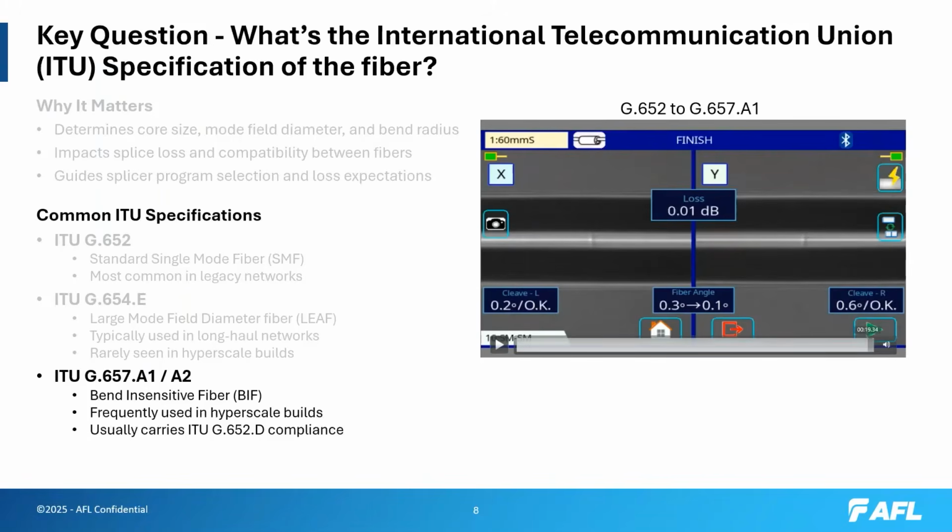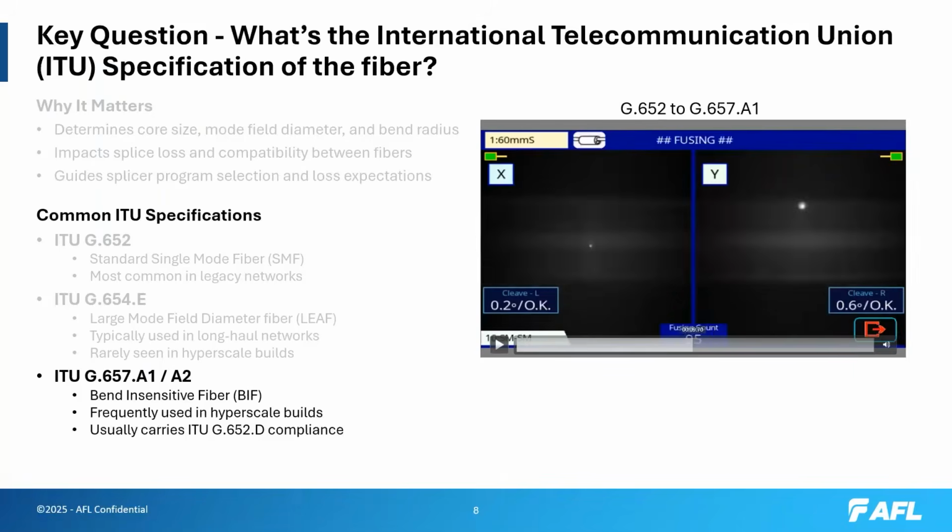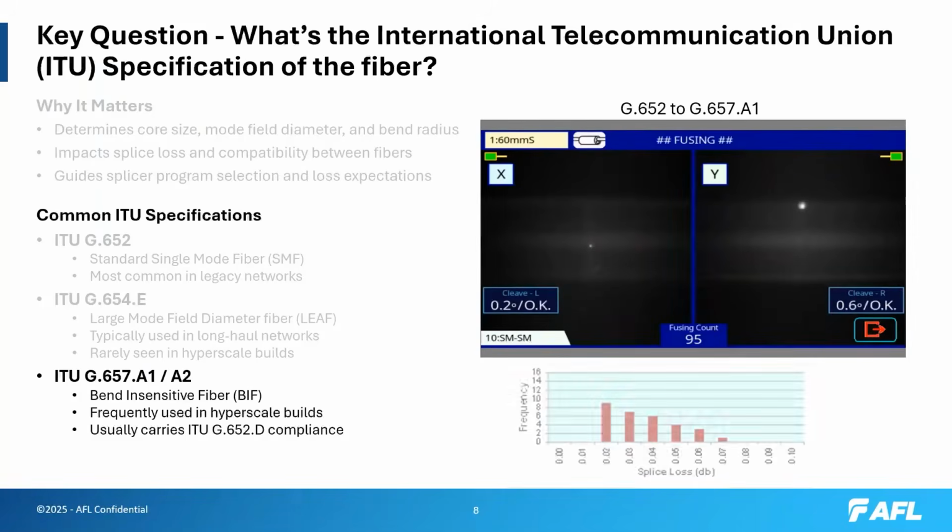First thing I want to illustrate is this little area here. If I point it out with the laser pointer, you'll see this little bright spot. This is what we would call a hot spot. This is fairly normal in this industry. It's a fairly small piece of glass that may have chipped off, or a piece of small debris that may be on the outside circumference of that fiber, and you'll see this flash up.